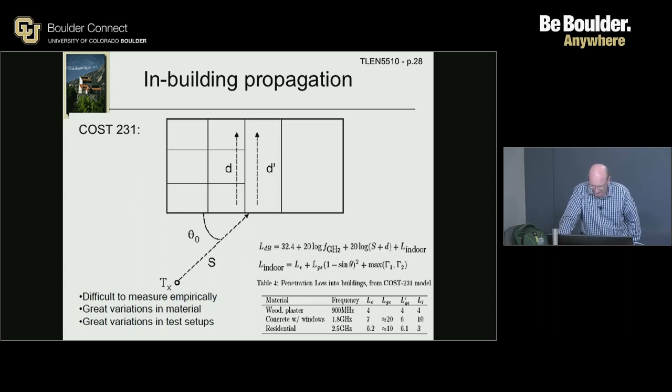And that one is very difficult to measure, but it's around 20 dB for urban concrete with windows type of building, and about 10 dB for residential, wood sidings, etc. When you don't really know, or you want an average on that, you can just take an average for a wide range of angles, and there you go.